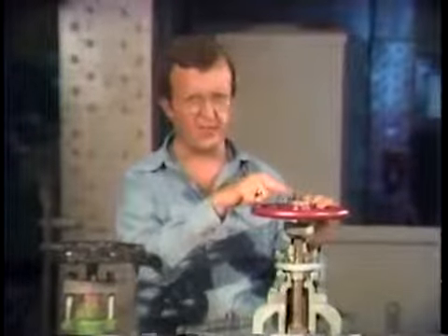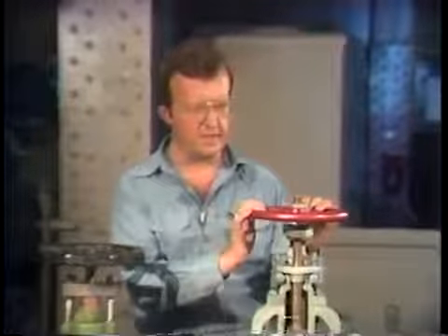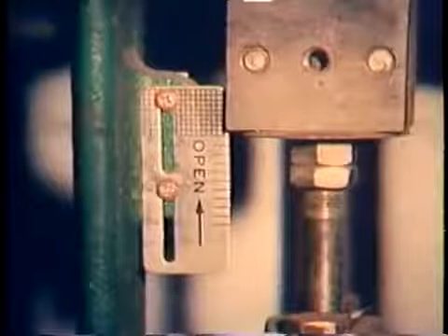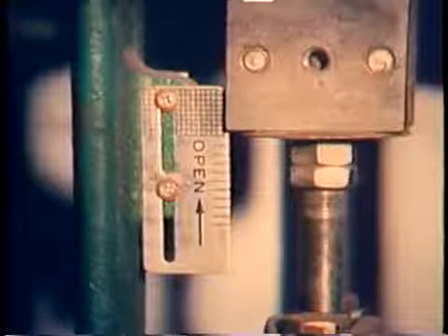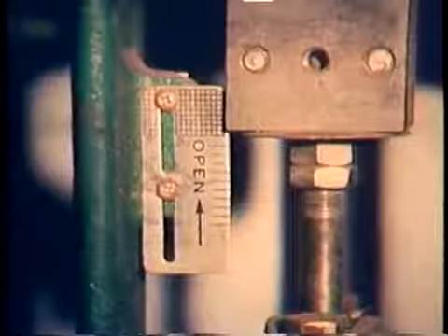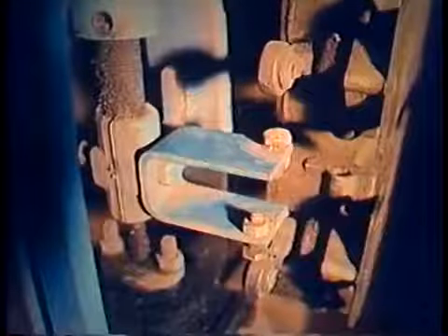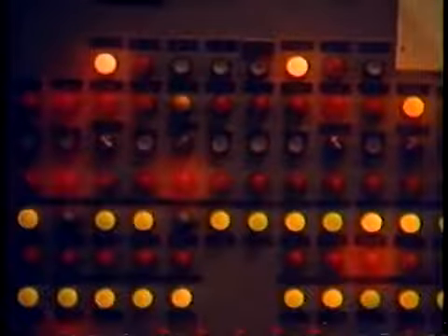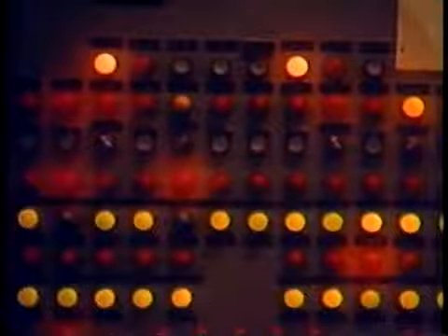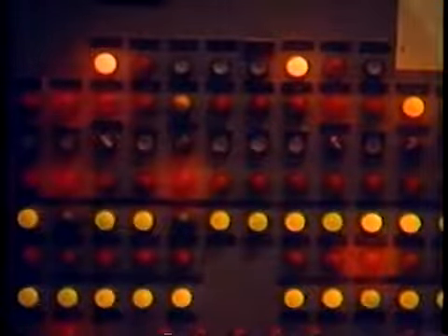Now, the rising stem valve does have one advantage. The amount of stem protruding from the hand wheel indicates the position of the disc. Now, you can tell at a glance whether the valve is open or closed. On the non-rising stem valve, an indicator should be attached to show the position of the valve. Usually, it's a simple arrow like this. Both types of gate valves may be equipped with a limit switch. The limit switch can be hooked up to light panels that show the position of the valve, so it can be observed by operators in other parts of the plant.